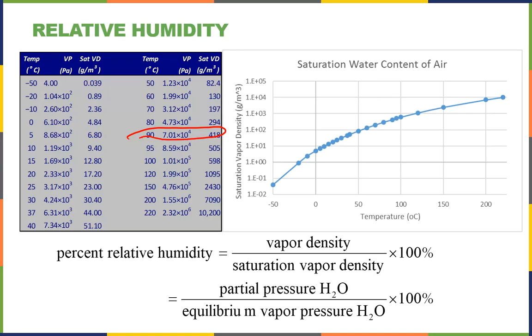Relative humidity does tell you more about how it's going to feel to you. If the relative humidity is 100%, you're not going to cool off from evaporation. If the relative humidity is 50%, you'll cool off some. If it's 20%, you'll cool off more. That's probably why we use it. But the dew point tells you that if you get down to this temperature, you're going to have 100% humidity, where the air is holding as much water as it possibly can.